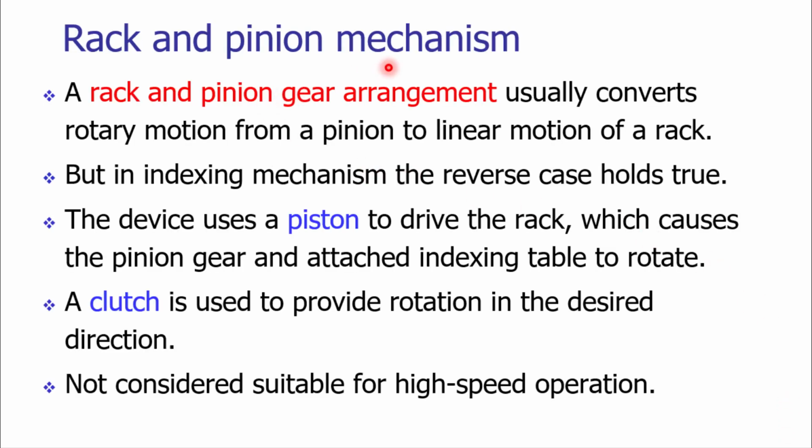Well, the next mechanism is rack and pinion mechanism. In general, the rack and pinion arrangement is used to convert the rotary motion of pinion into the linear motion of the rack. Pinion is an element which is rotating about its axis. Generally the pinions are driven by electric motor. And as we are rotating the pinion, it is converting that rotary motion into the linear motion of the rack.